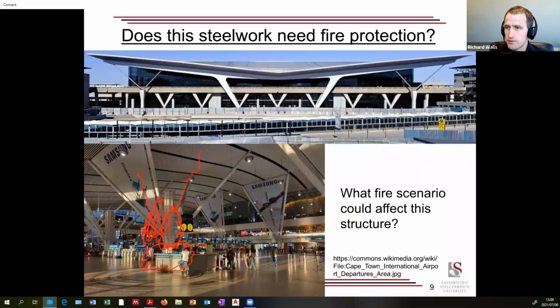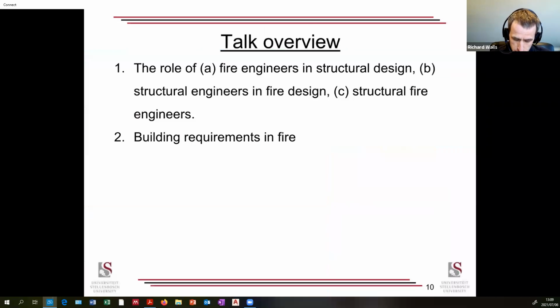On the roof level, imagine even a big fire now here at the bottom and the hot air rising up. By the time it reaches the roof, it's actually fairly cool. And you'll see earlier how it's very cool. The roof, when would the roof up here get hot? When would it get to the temperature at which steel starts losing strength? 400, 500, 600, 800 degrees Celsius. Not often. You'd need one hell of a fire in here, or you'd need the cladding on the roof to catch fire. You'd actually need the cladding system up there to burn. Then maybe you'd start getting to the stage of being able to affect the structural system.